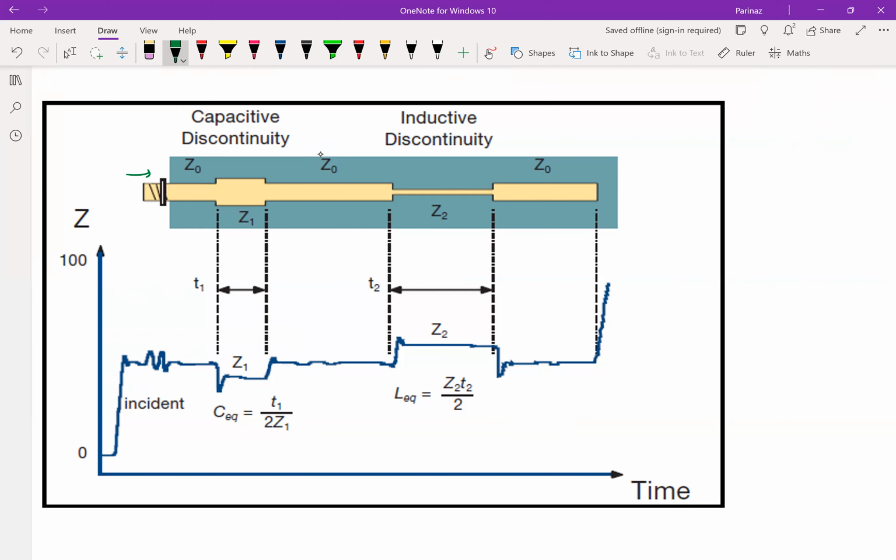And then as soon as it sees the line, it goes to, let's say, 50 ohm, right? So if this is our standard size for 50 ohm, as soon as we have a wider width of the trace, then again, just like the bend, it introduces some extra capacitance between the trace and the ground that is behind it.